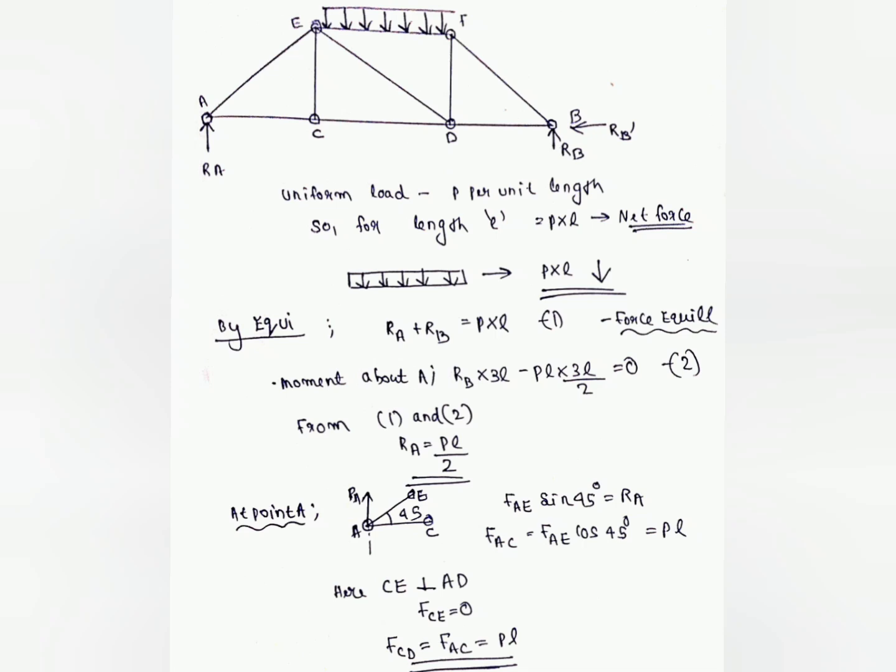So all I have to know is the basic law of equilibrium and the law of these links. If three links are connected together, the one which is perpendicular has 0 force, and the other two will be equal. Okay, that's the other law of mechanics.